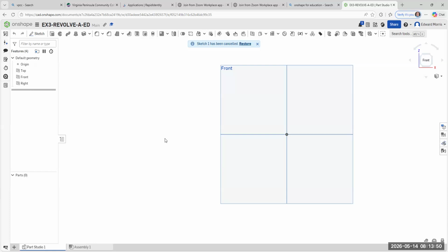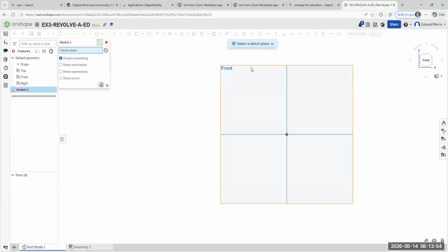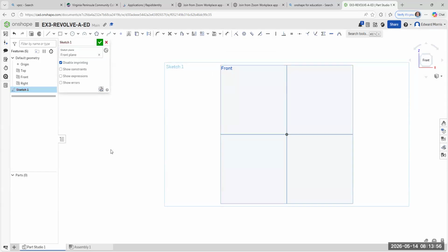All right. Now we'll try this again. Go to sketch. Click on this plane. All right. Here we go. I promise this time we're really going to do it. Go to the line command right here. Click on line, and then I'm just going to anchor the line at the origin, click. It doesn't really matter how long this line is, but I am going to give it a value here.